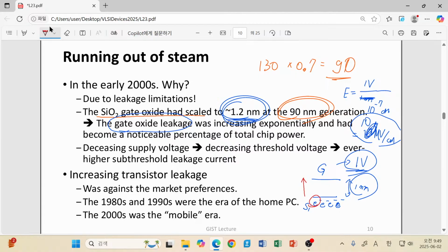And previously the oxide thickness was not 1.0 nanometer, it was 1.5 or more. Then there was no possibility to overcome this physical barrier. However, since now it becomes too thin, electrons can directly overcome this very thin oxide layer, 1 nanometer thick, and arrive at the gate. So now we have gate current. Gate current originates from electronic movement from channel to gate directly by tunneling. So it happens in this extremely scaled gate oxide.